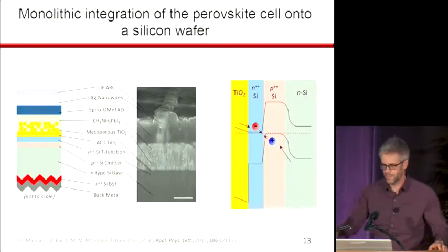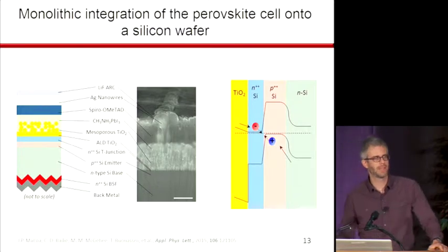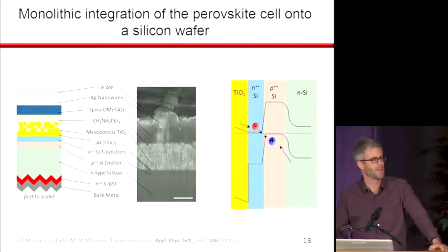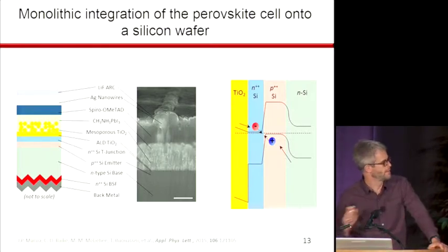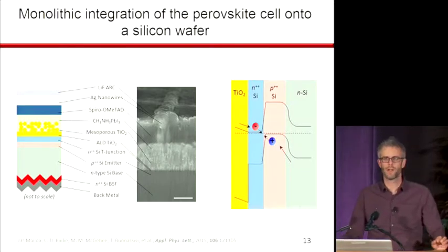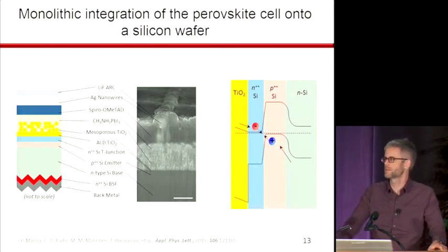With MIT, we made the two-terminal tandem, and Tonio Buonassisi's group took the lead in making tunnel junctions on top of silicon. On the band diagram on the right, you see that what we do is very sharply switch from highly doped p-type silicon to highly doped n-type silicon.